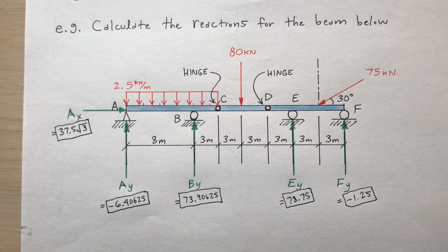So if I had had a continuous beam, it would have created a bigger mess to have just arbitrarily cut it at either C or D. The fact that I've got a hinge at C, a hinge at D, allows me to cut it and not make a bigger mess in terms of my calculations. Remember that a hinge carries no moment.